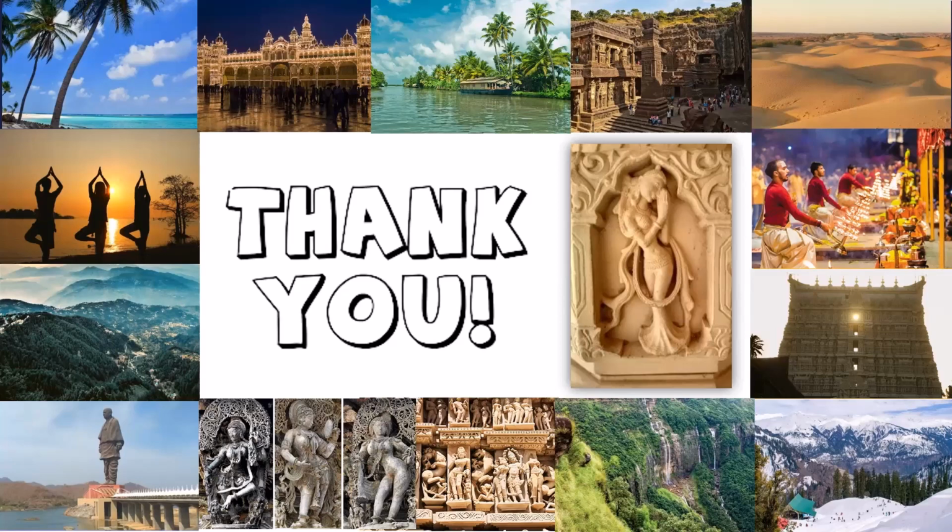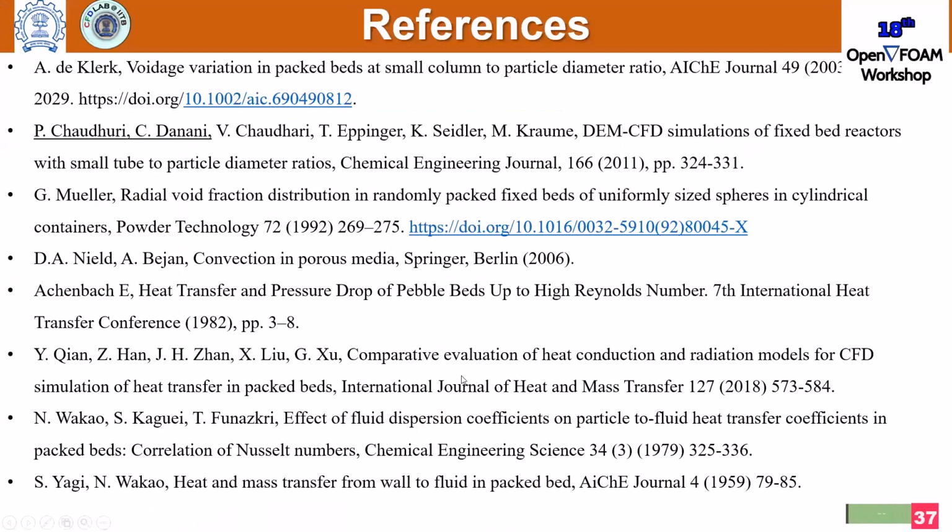Yeah, so there is one paper in the references. I have not written it, but there is one technique that is called shrinkage of the particle. We generally shrink the particle to 0.98 of the particle diameter. And with this, we can avoid the contact points between the pebbles. So that is why you are getting some error in the heat transfer.